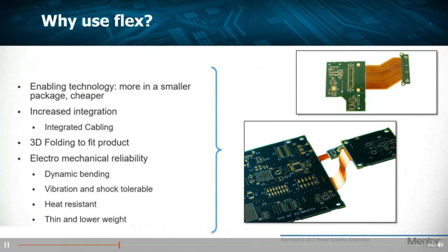Within the flex environment of PADS Professional that I'll be showing, we do have the ability to look at our board in 3D and see how it would actually fit in our enclosure to ensure that it's going to work as an end product. We also have the ability to take a look at dynamic bending. You can play around with the bend angles and the bend areas, just to see what's going to work best in order for you to fit inside your enclosure. Also, the flex capabilities these days.